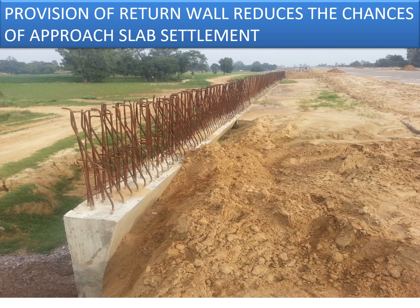So generally what happens is the approach slab doesn't settle because of weakness in its strength, but rather because of the formation of a cavity below the approach slab. So if we are able to control the cavities being formed below the approach slab, we will be able to control the settlement of the approach slabs.